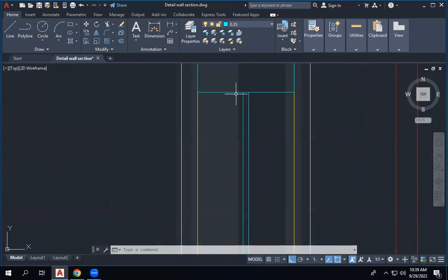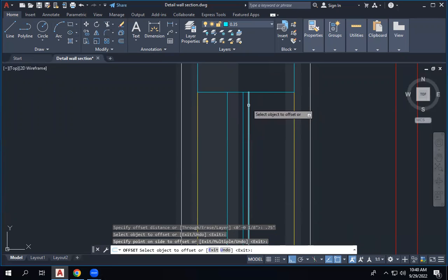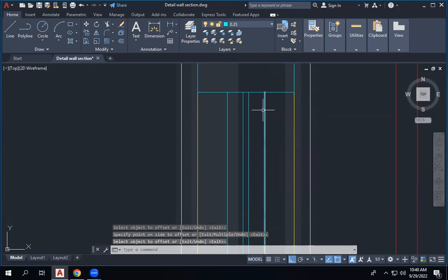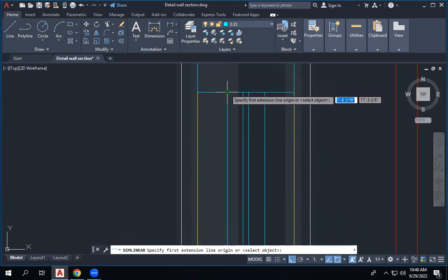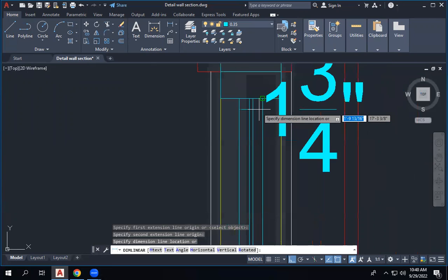Now I need the frame for the panel. So we take the aluminium sections to be 1.5 inch like that. So we have a quarter here, so we need another 1/4. We'll take 1.5 to both sides, then it's 0.75. Doesn't matter. So I will take 0.75 offset this side, 0.75 offset this side. 0.75, 3/4 inch.